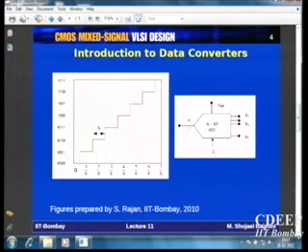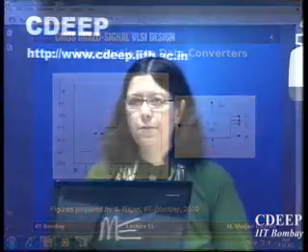So, however, working with quantized values in an amplitude domain, say voltage domain or current domain, also is not so easy. Otherwise, you will need a multi-valued logic. If you have, for example, 16 quantized levels, you need a 16-level logic. And when you have a 16-level logic, it is very difficult to control noise. The whole idea behind going from analog to digital domain is to have freedom with respect to noise. The noise is one of the problems in the analog domain.